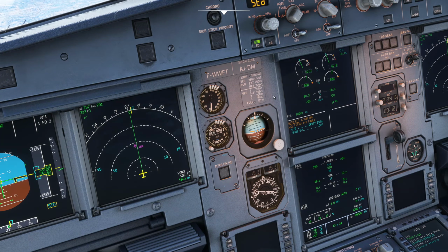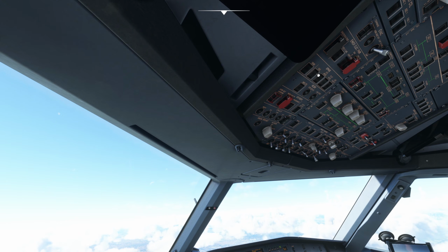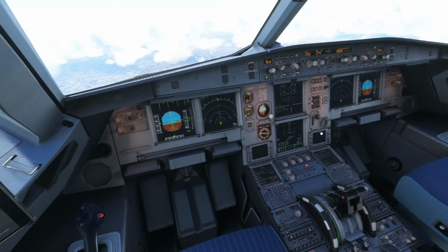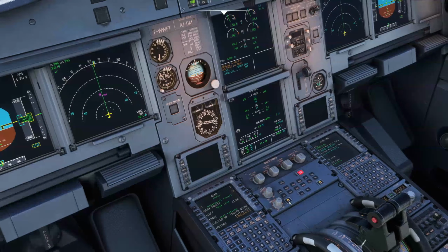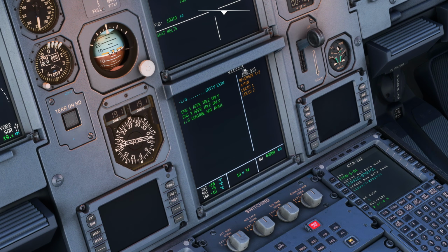And here we are. So landing gear gravity extension, GPWS system off. So GPWS system, up here it can go off, and pretty much similar. So I'm going to clear out the auto flight, clear out the LGCIU 1 plus 2, and here we go. Here's some of the additional problems. So we've lost the reversers, lost the auto thrust.